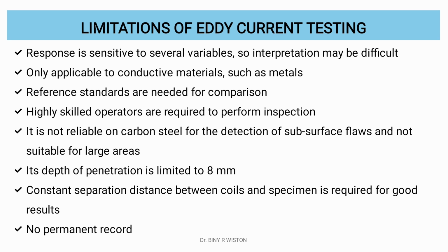The limitations of eddy current testing include the sensitivity response to a number of variables, and interpretation may be difficult. It is only applicable to conductive materials such as metals. The reference standards are needed for comparison.